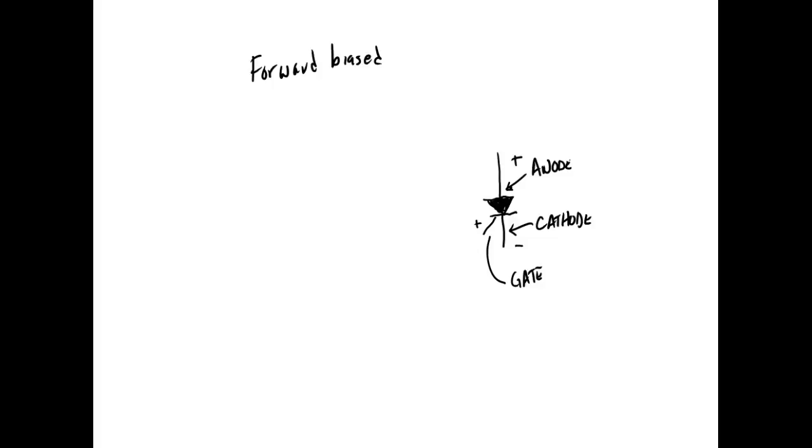Now once it's on, how do we turn it off? So let's say I come up here and take that away. Will it turn off? No, what turns it off? We have to drop it below its holding current.